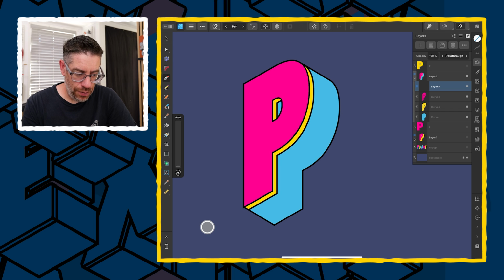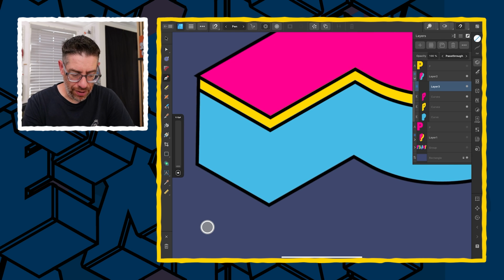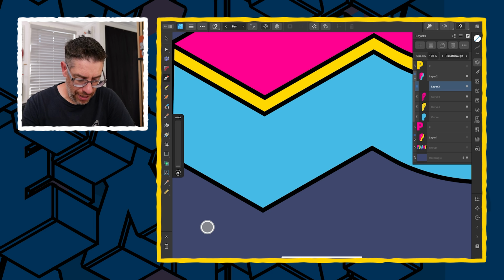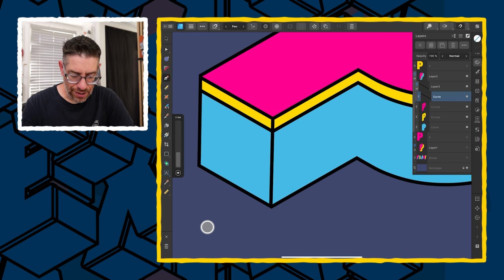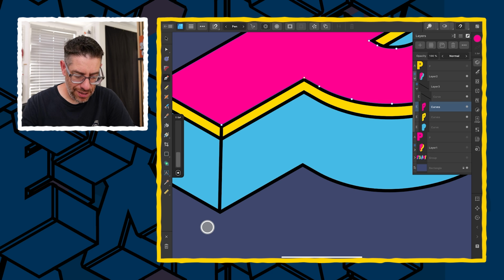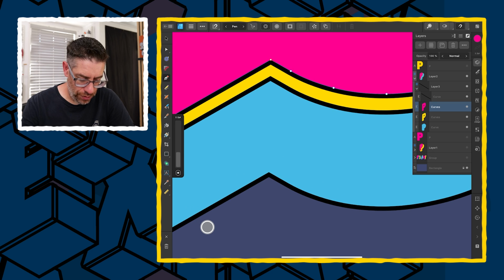Up at the top here we have use fill and use stroke, or use line. We're just going to use line and keep fill unselected. Hopefully when we draw it should be the same outline as what we've done there. So we're going to just rotate that, and then I'm just going to draw a straight line like that there. I'm going to select back on the P so that when I draw a new one it won't join up that line.